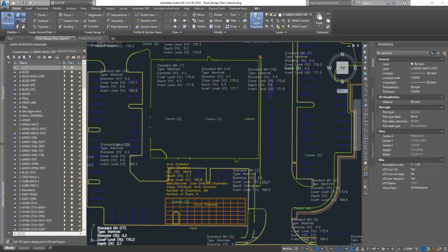And we can see what this looks like in CAD. So I've exported this object. You'll see it looks quite similar to what's shown in XPdrainage. Something else which comes across is a number of annotations and notes for each of these objects. So for instance, for this arch chamber facility, we have top, bottom elevations, the manufacturer type, and so forth. The idea is to publish information out to CAD so that a designer, someone working on perhaps a site grading plan, could seamlessly begin to do their work and complete a finished grading plan or see on the site what the stormwater team is proposing.